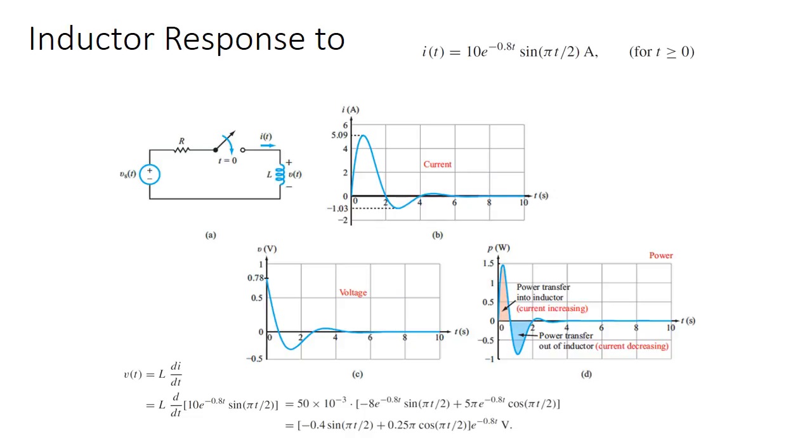So again, we're plotting that equation that we've given at the top, i(t). If we plot this equation, essentially it's going to fill up to a certain point, and then it's going to dip down again, because there's no change in current, and that's what inductors need, a change in current. Because there's no change, it's going to peak out and slowly approach back down to 0. Interestingly, it might go beyond 0 in this case, which means you have this oscillation for a brief period of time before you reach the steady state current, where it's essentially 0 current.